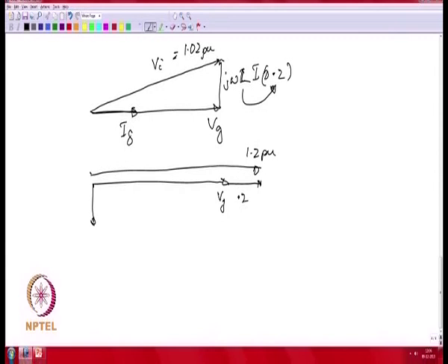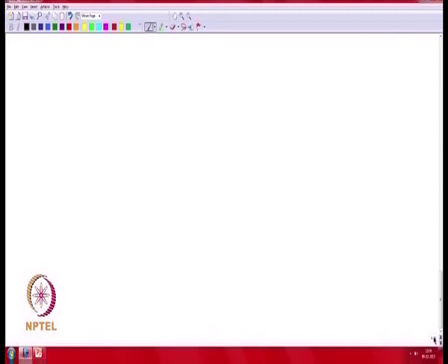Suppose you are not operating as a STATCOM, or even though you are operating in a unity power factor mode, typically for a DG you might consider some variation in the power factor. Say you have the grid voltage Vg, and your Ig that you would ideally like to inject at unity power factor, and say you have a range of Ig going from 30 degree lead to 30 degree lag.